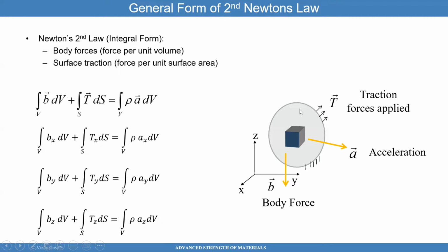Then you have the traction forces that are acting external to the body. These traction forces can be decomposed, so they're acting in the x direction, in the y direction, and the z direction. So these tractions can also be decomposed, so they follow the x, y, and z. So I'll take the tractions in the x direction, integrate it over the surface, because these tractions are only acting on the surface, dS, and that summation of forces